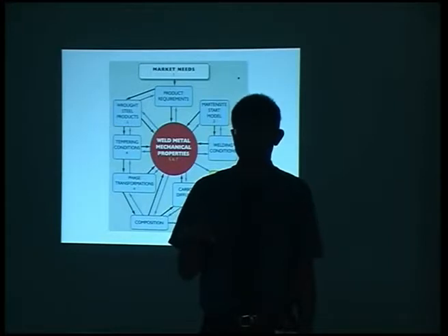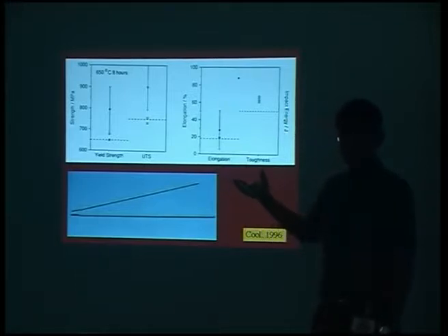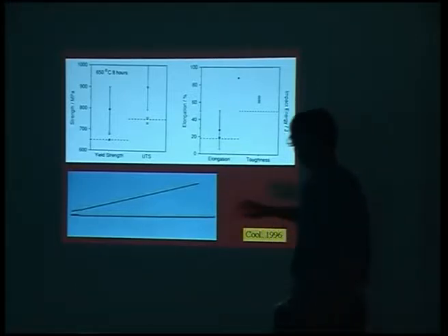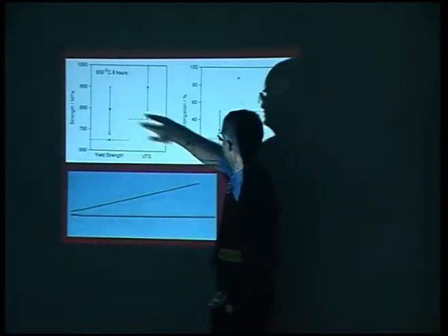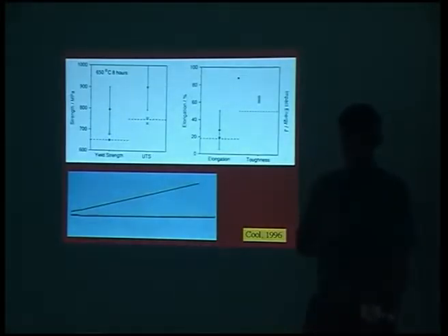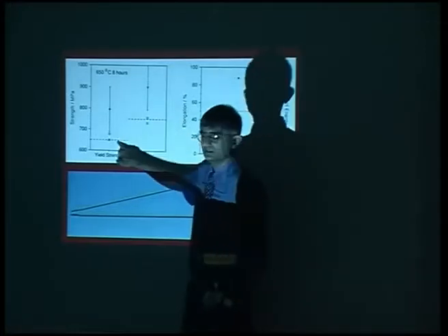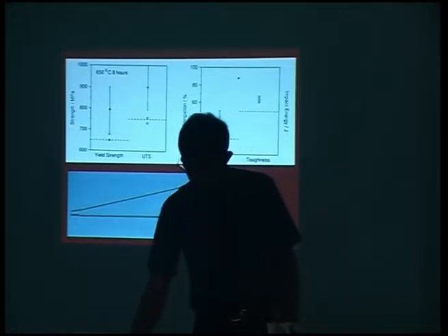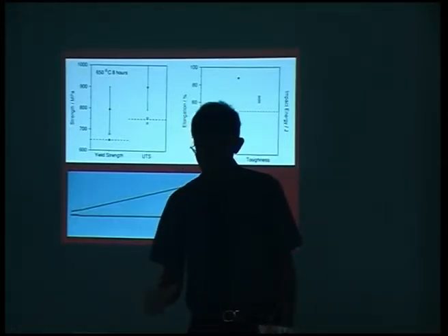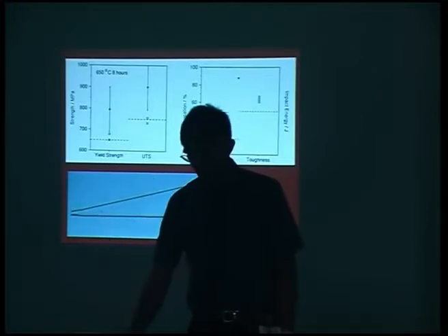Yeah? So using a combination of all those models, we made some manual metal arc electrodes purely by calculation. These were the engineering requirements, and we met them on the very first go. Okay, so all the measured properties fall above the design requirements which were given by the engineers. Now, being in a university, the idea here was that they would do a post-weld heat treatment which was 650 degrees centigrade for 8 hours. Yeah? So we've met all the conditions that were specified.